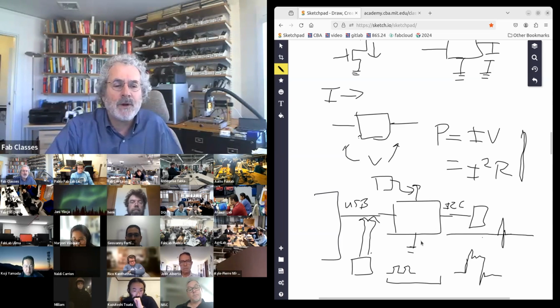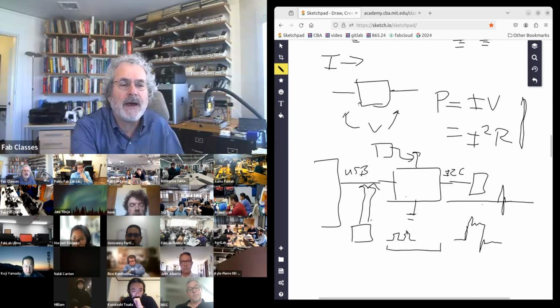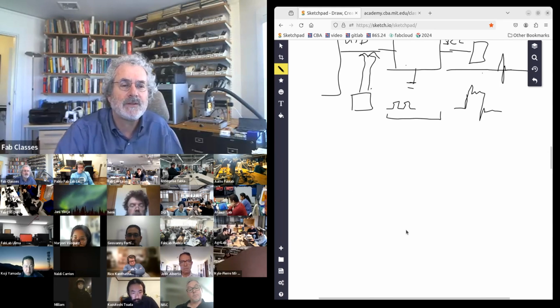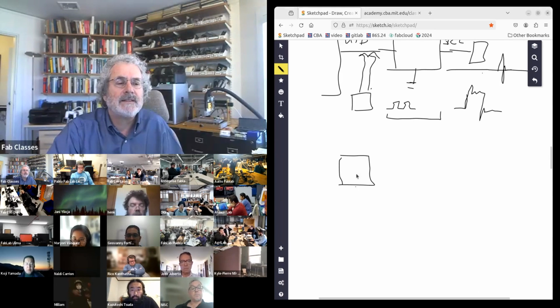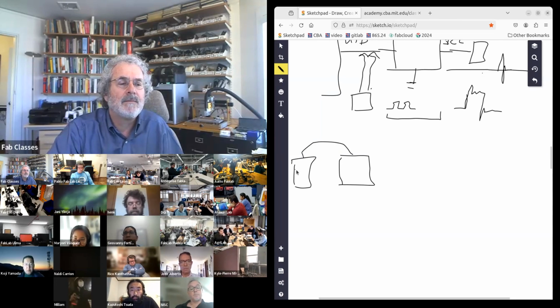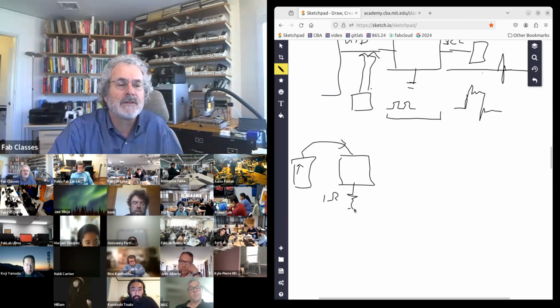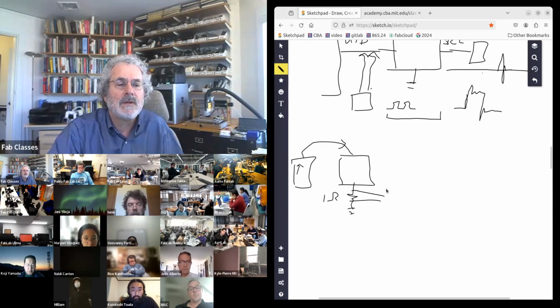And then one of the most important things to do is to measure the power consumption. So if this is your device, if you use a smart power supply, the device itself will measure the power going in. If you put a tiny resistor, like a 1 ohm resistor going to ground, you can measure the power coming out.